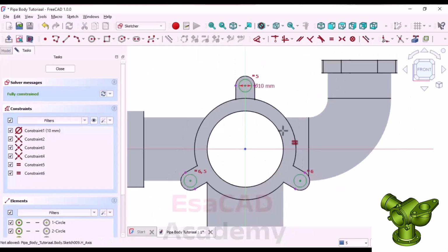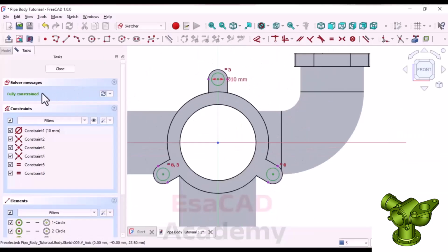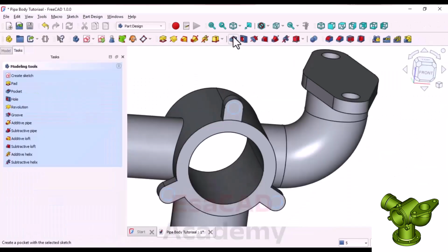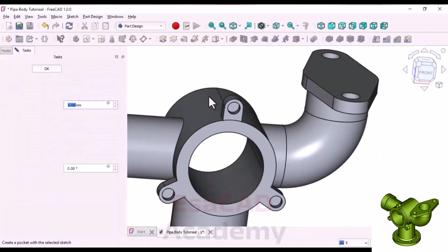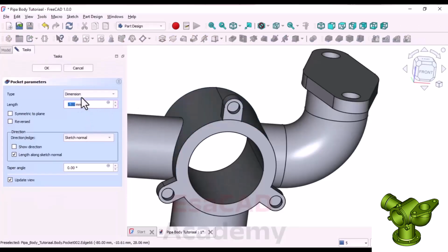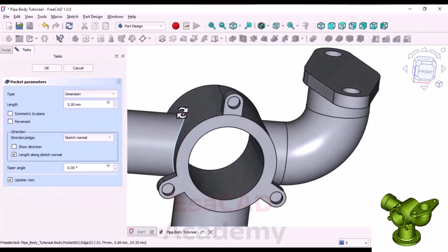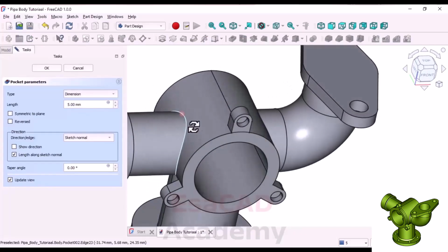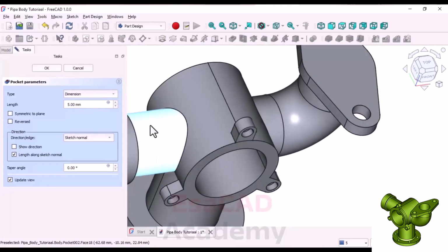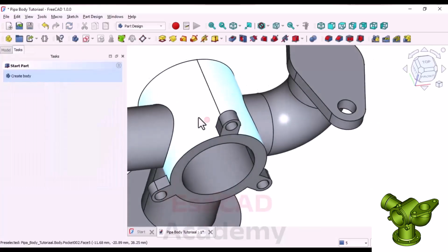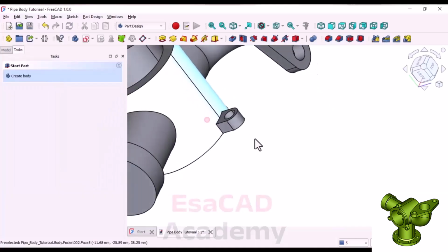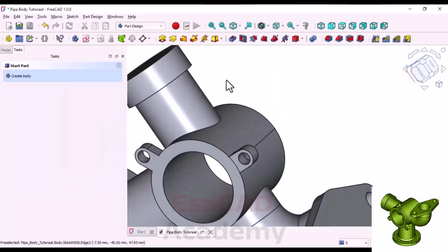Alright. After setting all constraints, choose the extrude option and proceed to create. Avoid using through all at this point, as it will penetrate to the other side. Let's go ahead and provide everything here. The thickness here is 10, as specified. OK.